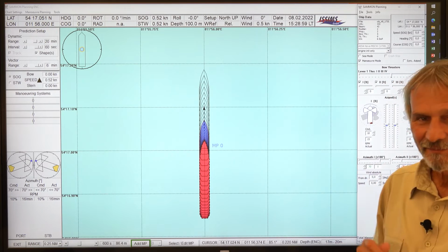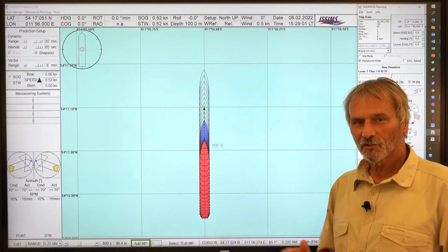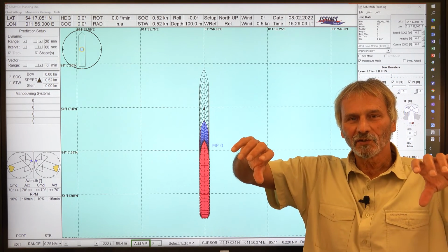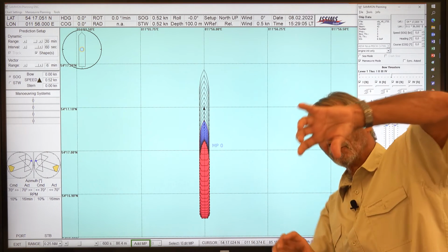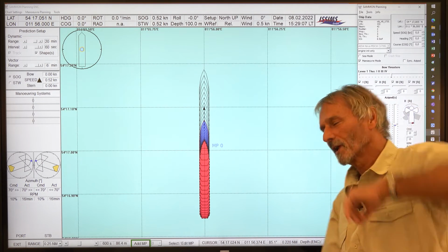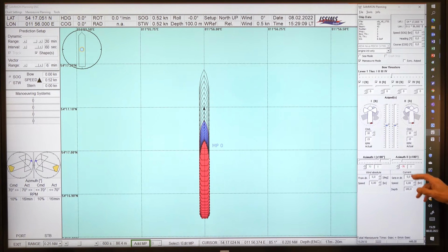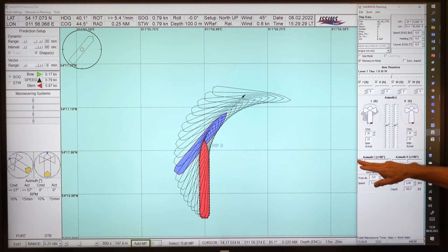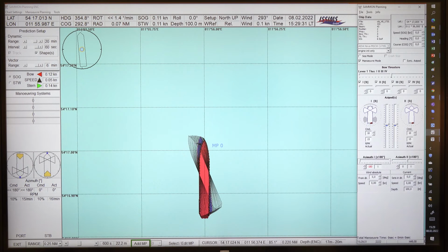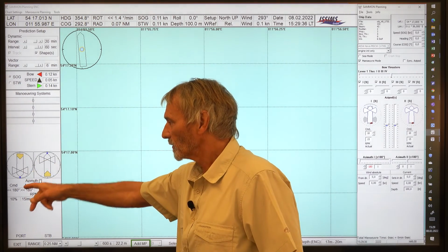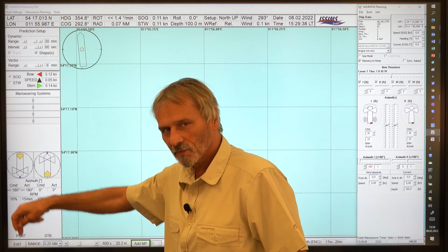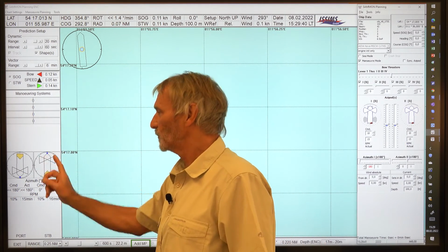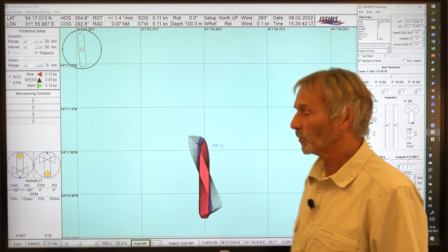Crazy question: can we also use this toe-in, not in this direction, but in this direction? You know what I mean? If I'm going this one ahead, and this should be going astern, like this. So what you see now is one pod is pulling the ship astern, and the other one is pushing the ship ahead on the starboard side.